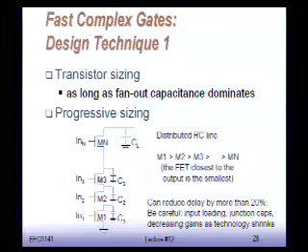And the second one would only appear in 2, and the third one would only appear in 3, and the fourth one will only appear in 4. The bottom one would appear in all 4. So what this means is that if you try to make all these resistors the same, you are basically wasting capacitance on these nodes, right? Because you are generating a high capacitance node to make this transistor the same resistance as this.